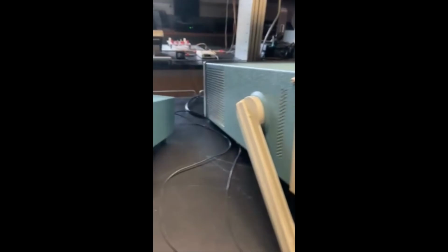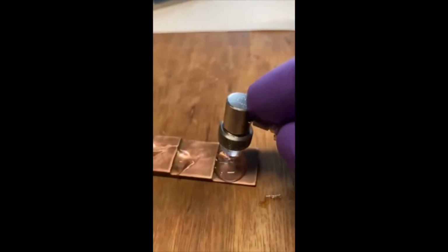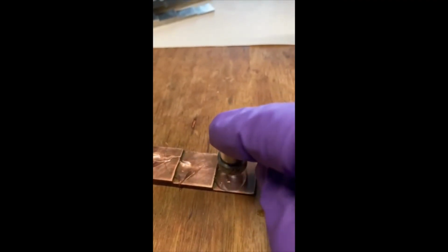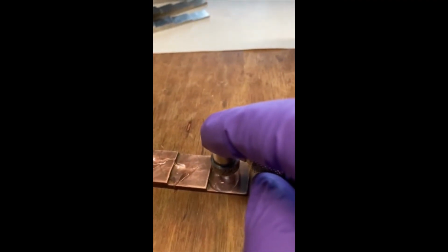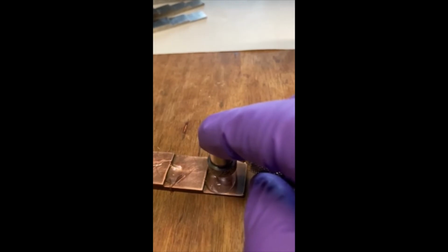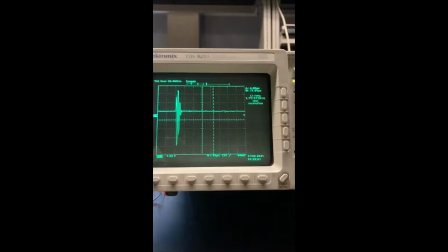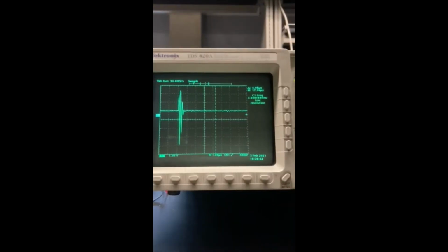To begin, we're now going to place the transducer in intimate contact with copper step number 1 surface. We're showing here now the initial pulse. Next, we're showing all of the reflected pulses as they come back. So in this case, each pulse goes across the sample and comes back, and then it is reflected back and forth within the thickness. And there's a decaying amplitude. So you can see this nice decay function.